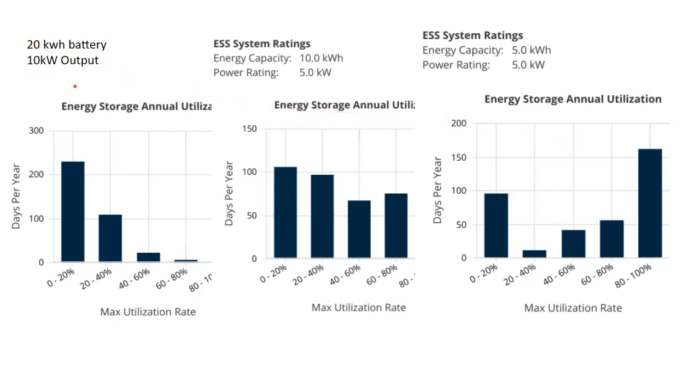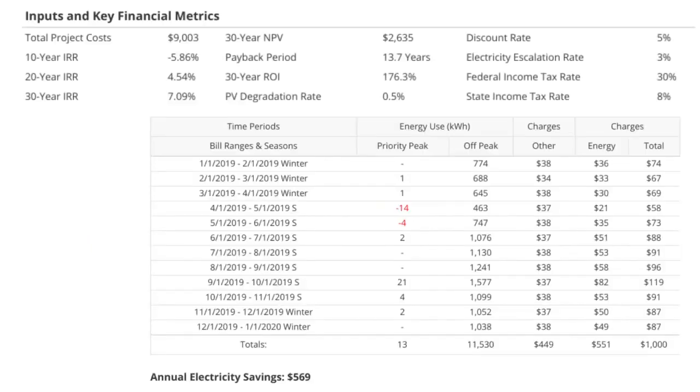And so on this larger battery, on the days of maximum discharge, maybe one day out of the year, it's being used to 80%. Whereas here, with a 5 kilowatt hour battery, something a quarter of its size, it's being used almost every day to its fullest extent. Hopefully it's being used 5 out of every 7 days, right? And so what is the right size battery, because lithium ion is very expensive. So you want just enough to get through your 3 hours of usage, because that's what the rate structure is, but not more than that.